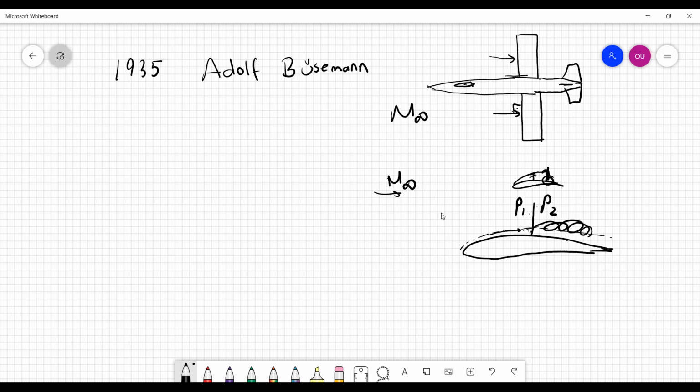If you zoom in to this region, let's say this is the top, the normal shock wave comes here, and because the flow is separating just near the normal shock wave, when the supersonic flow sees this separation line, it generates a small oblique shock wave. It's basically acting like a ramp. Then it gets combined with this and generates another oblique shock wave at the back.